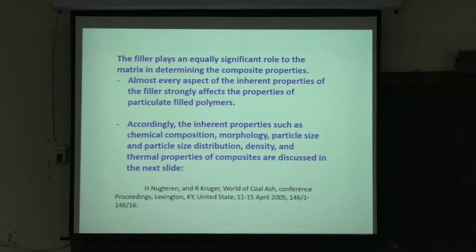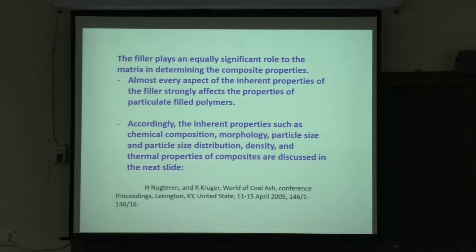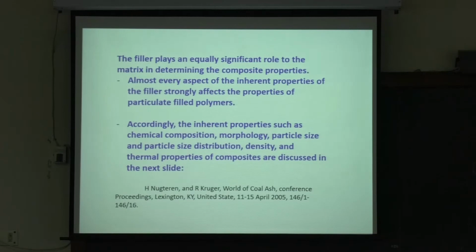The filler plays an equally significant role to the matrix in determining the composite properties, and almost every aspect of the inherent properties of the filler strongly affects the properties of particulate filled composites. So now the inherent properties like chemical composition, morphology, particle size and particle distribution are discussed in the next slide.